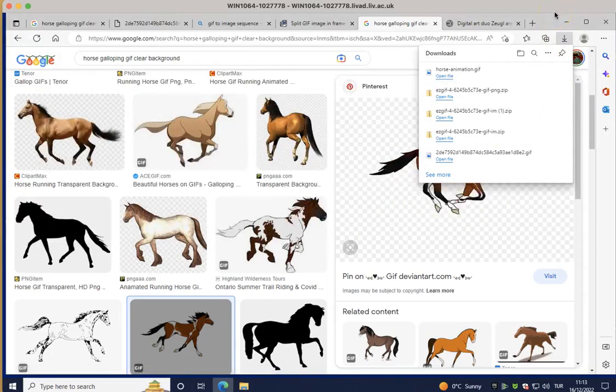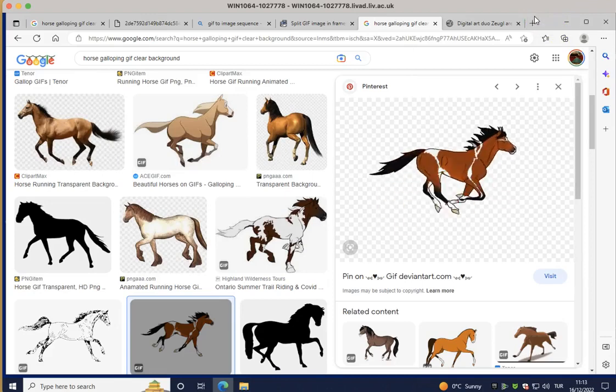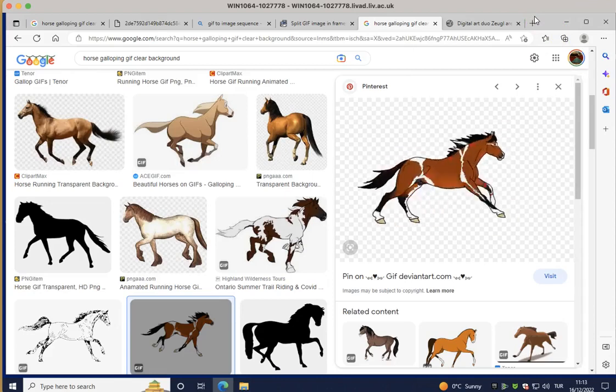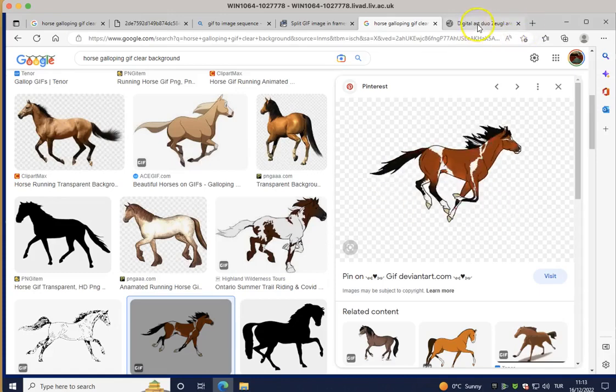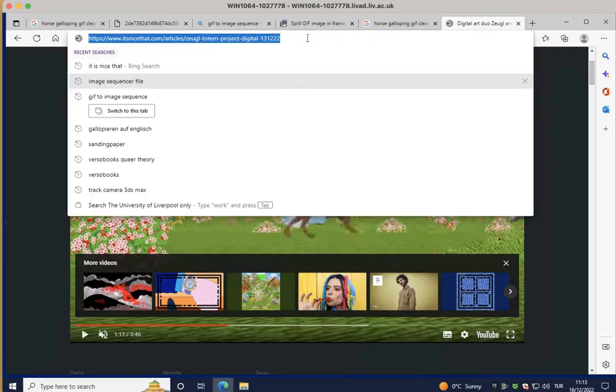But 3ds Max does not understand the GIF, so we need to take each frame out of this animation, which is a more proper way of animating things. Also for 3ds Max, we were taking the animations as videos, but if you have more time and you would like to do some post-production, it would be best that you take the animation in frames.